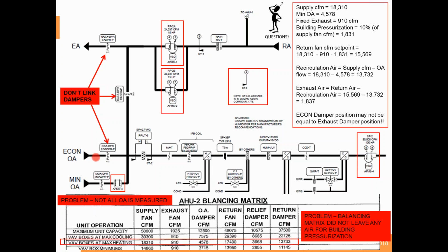If they're using a single output, if you're not in economizer mode, what are the values you're going to be seeing? And if you need to, like I came up with, I need to relieve 1800 CFM of air, you're going to be like, is the damper going to leak enough for me to do that, or do I actually need to crack those things open? So that is why. Okay, thank you, John.